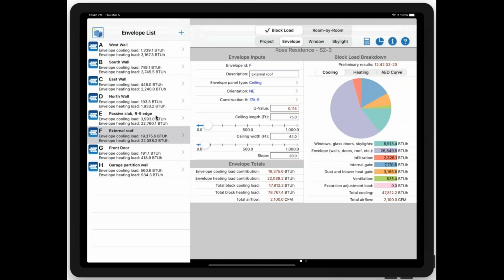Okay, got it. And the U value, just to go back a little bit, if your wall is not listed, today they're requiring outside insulation, and those are different numbers maybe than what you've got on your choices. You would just have to do a calculation and come up with your own U value for your wall? Yeah. U value is one over the R value. So if you know the R value of your insulation, if it's R30, 1 over 30, that's your U value.